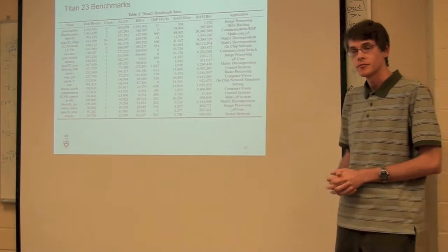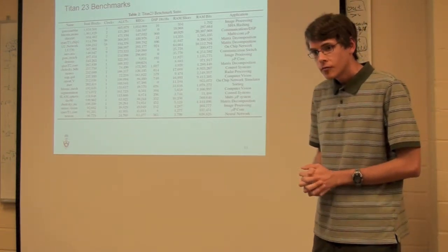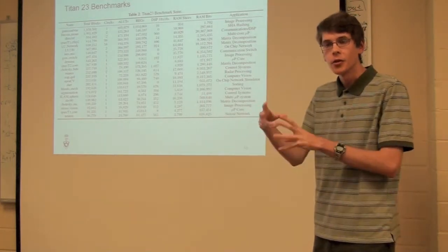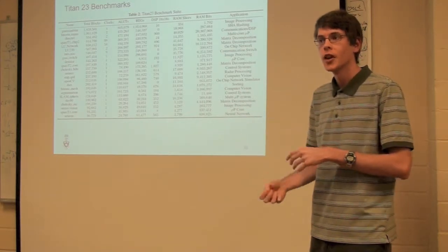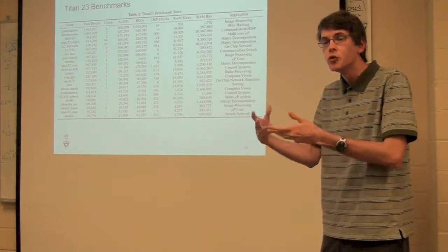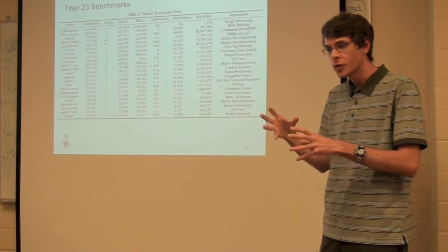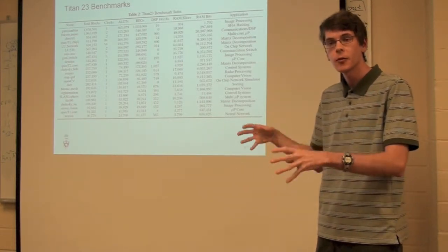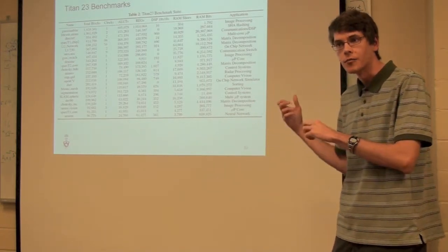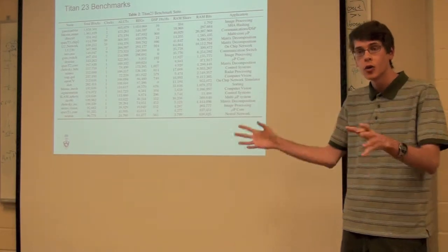Well, the more important question then is how do you handle all of those weird exotic blocks that result from this in your flow? They are generated by Quartus. So you can have all sorts of weird things like double data rate I/O blocks, and Quartus gives you a primitive for that. We don't put too much effort into modeling that completely accurately. Basically, we make it work in the flow and stuff those all into the I/O pad and leave them there, because the real focus would be mainly on the core performance if you were evaluating this. But it's all supported, so it will work.